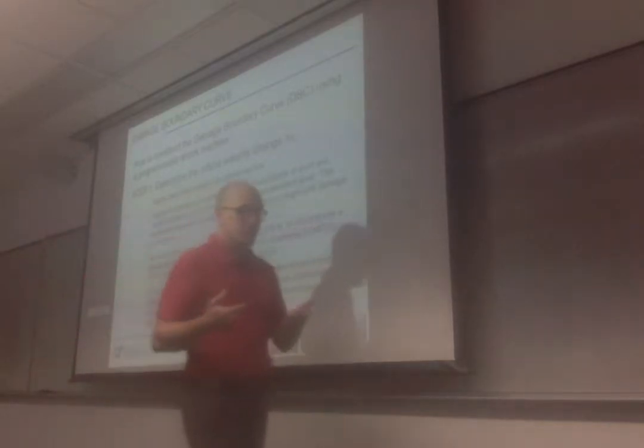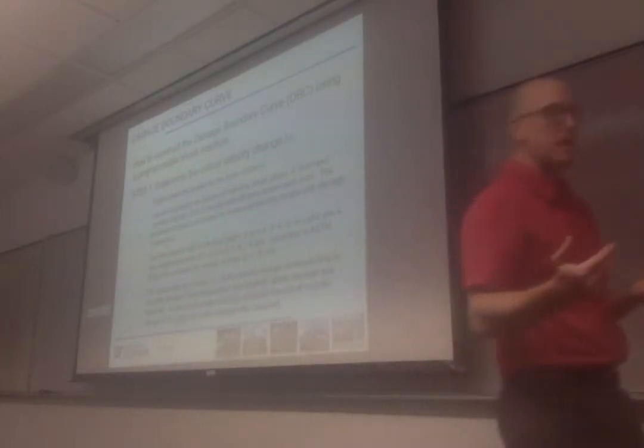Some people are like this, but in an ideal world that would be the case, because if you have multiple drops on your product, you may get fatigue. You may have some parts that at some point are going to get damaged, not because of the last impact, but maybe because of the accumulation of many impacts.